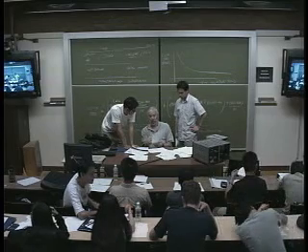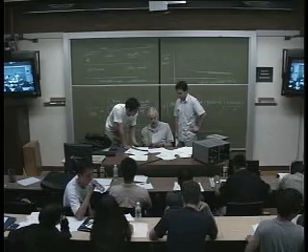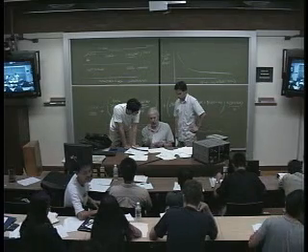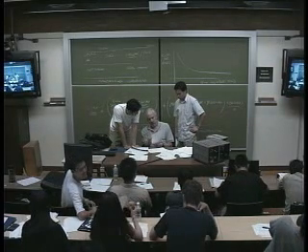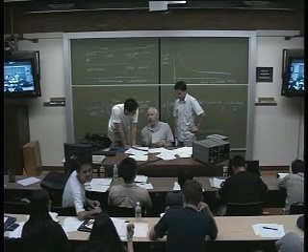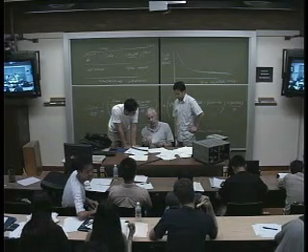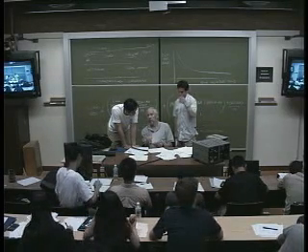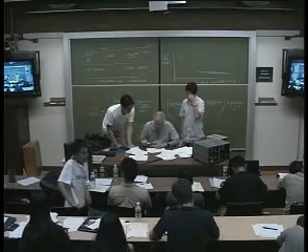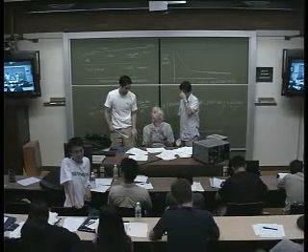So the RO goes down? No, because the big GM will be reduced. Big GM is only dependent on this GM, though. Okay, so why does it matter? It's that, as modified by my final statement: if all of this current went here and then all of it went out to there, then it'd only be dependent on that. But in actual fact, it hits here, and it'll be a current divider between 1 over GM this way and R0 this way. Current divider between 1 over GM and 1 over R0. Okay, that makes sense. Current divider.